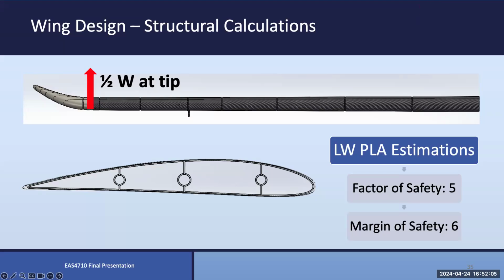Okay. In general, the structural analysis ought to consider something other than just straight and level cruise. It's one thing to say we've got a factor of safety on our straight and level cruise, but if you're telling me the plane is capable of pulling 3.5 Gs, that's a design load I would look at. If you want to say we'll put 3.5 times half the weight of the plane at the tip of the wing and show it's good for that, that's a conservative way to do the analysis, and I'm okay with that. But definitely consider what your load cases should be.